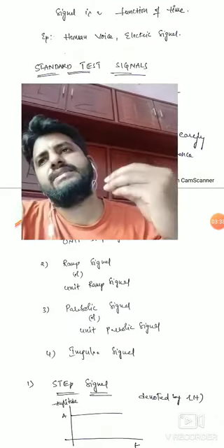So each and every time you take a reading, you have to take the position which is perpendicular to the pointer itself. So you can see the reading straight forward. If you bend to the left side, you will get wrong readings. If you bend to the right side, you will get wrong readings. These are observational errors.